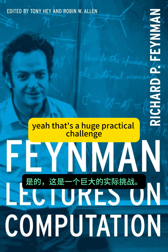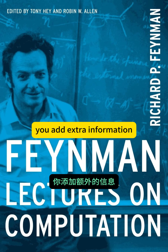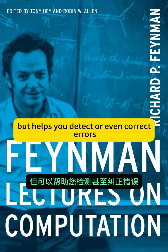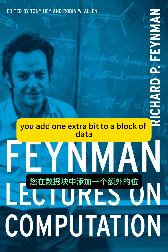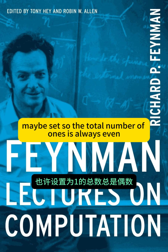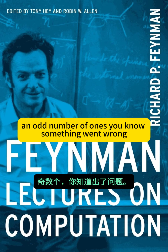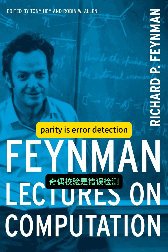Yeah, that's a huge practical challenge. The answer is redundancy. You add extra information that isn't strictly part of the data itself, but helps you detect or even correct errors. Like parity checking. Parity is the simplest example. You add one extra bit to a block of data, maybe set so the total number of ones is always even. If you receive the block and the parity is wrong, an odd number of ones, something went wrong. But you don't know what went wrong. Correct. Parity is error detection.